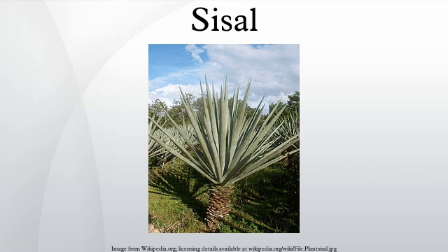In the drier climate of northeast Brazil, sisal is mainly grown by smallholders and the fiber is extracted by teams using portable raspadors which do not use water. Fiber is subsequently cleaned by brushing. Dry fibers are machine-combed and sorted into various grades, largely on the basis of the previous in-field separation of leaves into size groups.